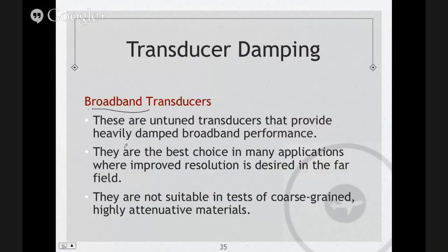And broad-banded transducers, right? They're not suitable in tests of coarse-grained, highly attenuated materials, right? So castings, you probably won't want to use broad-banded transducers in casting materials.